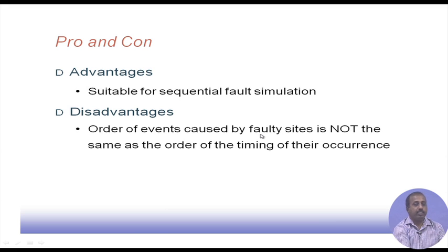Advantage, it is suitable for sequential fault simulation. Disadvantage, the order of events caused by faulty sites is not the same as the order of timing of their occurrence. What we mean is that the circuit has some order: when we simulate one particular gate, its predecessor must have been simulated first.